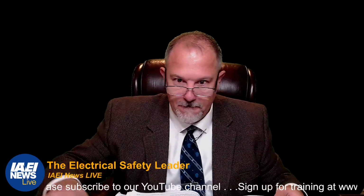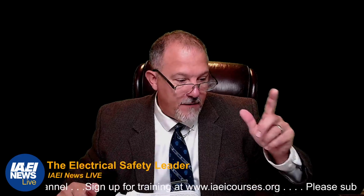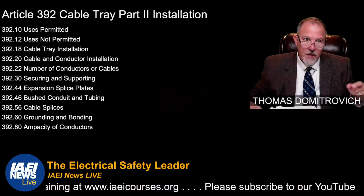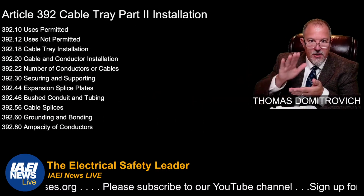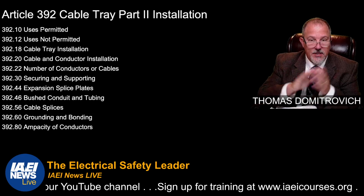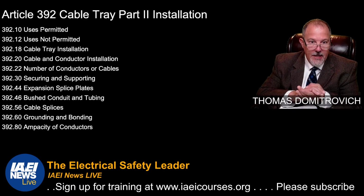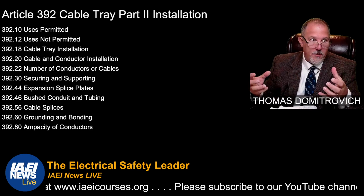All right, now, if you look at part two, these are all the different sections that are a part of part 2. They've got uses permitted, uses not permitted, cable tray installation, cable and conductor installation, number of conductors or cables. That's going to be important. Why is that going to be important? A lot of different reasons. You've got heat, you've got weight, the whole bit. Expansion splice plates. Why is that important? You don't want it pulling apart in the field.